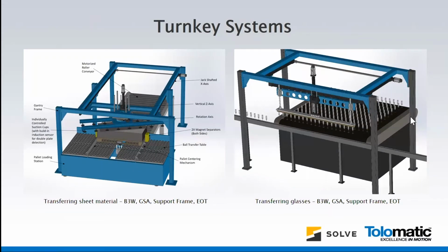On the left side here is a handling gantry system that would take sheets of metal and move them from a ball transfer table to a conveyor. What's interesting about that system is you can see that large welded steel frame, the blue frame here. We've created that frame around the mechanics to support it. And then you have a couple of jack-shafted actuators, and across this is a y-axis bridge that is also supported through a frame.